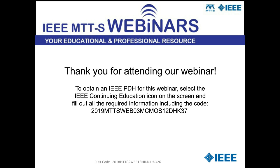Is the phase shift between the clock signals realized on chip? Yes, it is. That's one of the benefits of building these CMOS circulators, which is that all the clock generation is done on chip. We come in with one external clock, and then we take that external clock and achieve the phase shift, which is typically done by dividing the clock down. If you have a differential input clock, then when you divide the frequency by 2, the 180 degrees differential phase shift gives you access to 90 degrees phase shift.